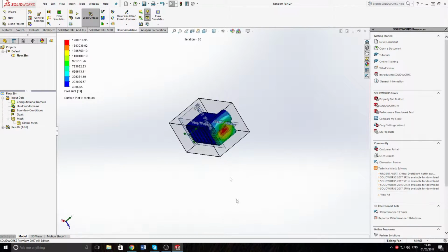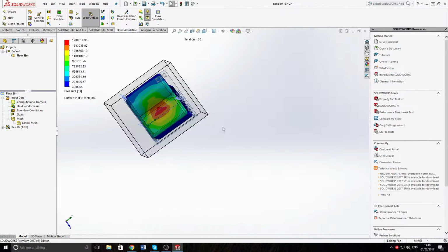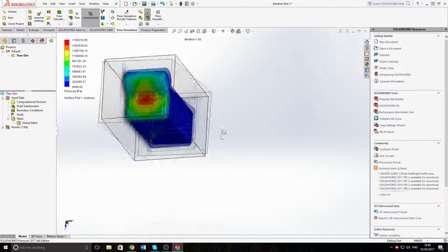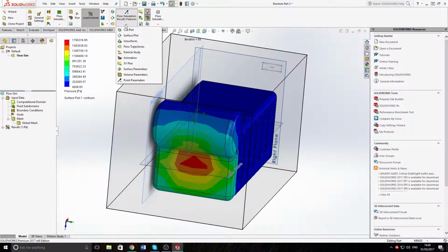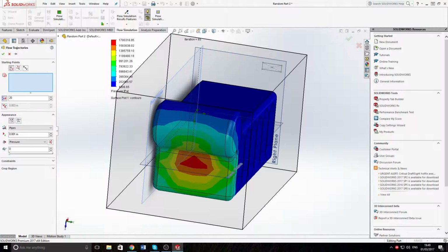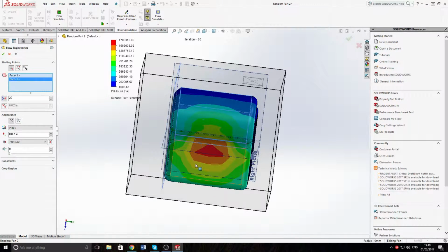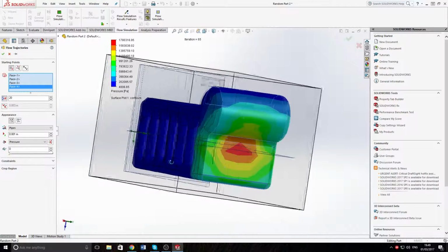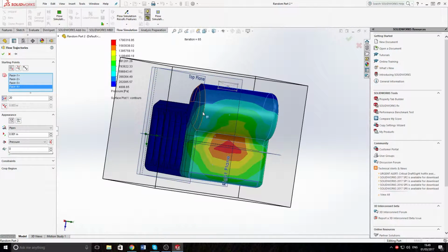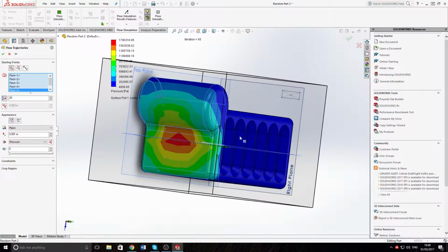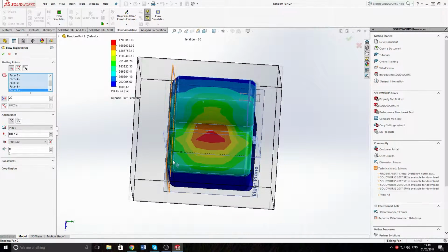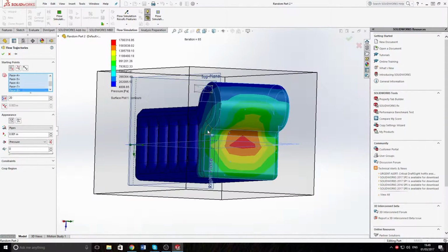And you can see that the wind was hitting at this side, so you can see how it's going to hit the front of the face. That isn't that useful. So if you go flow trajectories, starting points, let's go with all these front faces, just so we get a sort of flow of it. This is one reason why you might want to put a plane in. So that's all of that side of it pretty much. Just a couple there. No.